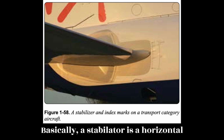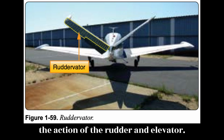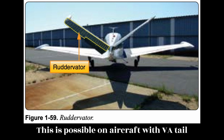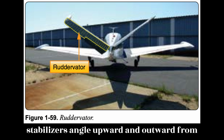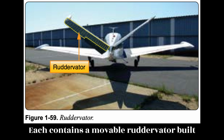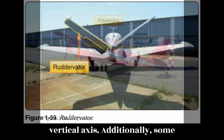Basically, a stabilator is a horizontal stabilizer that can also be rotated about the horizontal axis to affect the pitch of the aircraft. A ruddervator combines the action of the rudder and elevator. Figure 159. This is possible on aircraft with V-tail empennages where the traditional horizontal and vertical stabilizers do not exist. Instead, two stabilizers angle upward and outward from the aft fuselage in a V configuration. Each contains a movable ruddervator built into the trailing edge. Movement of the ruddervators can alter the movement of the aircraft around the horizontal and/or vertical axis.